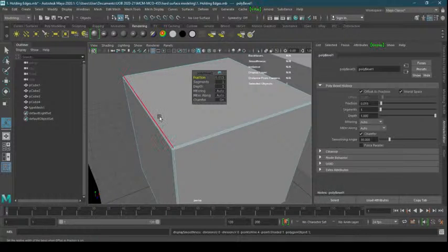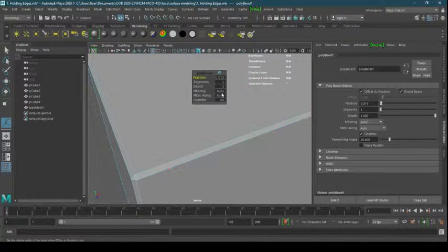So what I can do, instead of just calling it a day or ending it here, I will go to segments and increase segment. Right now one segment is there. If I make it 2, and then press enter, you will see there will be another extra edge here. Okay, so with 1 it will look like this. There is no edge between these two, or any one of these. But if I add 2 here, it will give me one extra edge here.